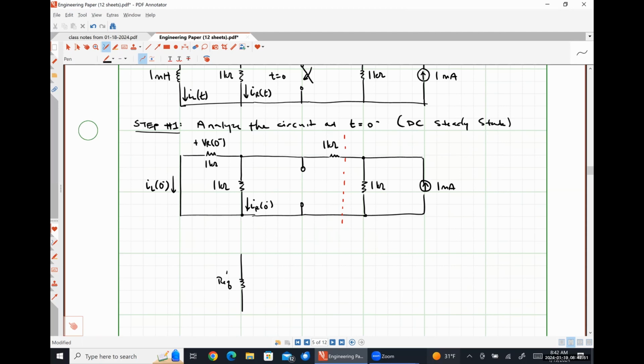The reason is that our inductor current equation was developed for the transient condition, and we are not in the transient condition right now. We're at the moment before the transient condition occurs. So the resistance seen by that inductance might not be this REQ. And so I'm just trying to make that distinction so that we don't get too mixed up.